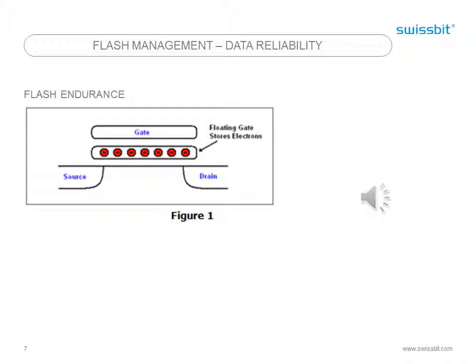Over time, the floating gate retains more and more residual electrons, charge trapping, which will shift the threshold voltage higher. As this VT becomes higher, the proper level detect range also becomes smaller. With SLC, the threshold level shift is not as critical and leaves more margin. Thus, SLC NAND has better endurance, reaching about 100K PE cycles.